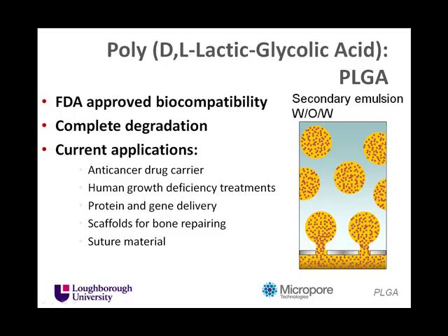And the clever bit here is the low pressure drop, the ease of generating that secondary emulsion. Because it's such a straightforward system, we don't risk poor encapsulation efficiency, because the worry is that the water internal phase, one of these little drops, goes into this external phase here, and that would cause us low encapsulation efficiency.